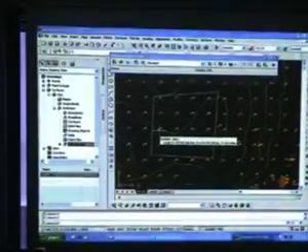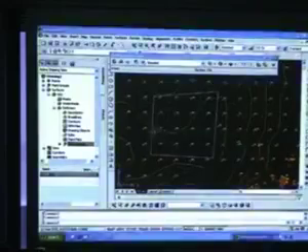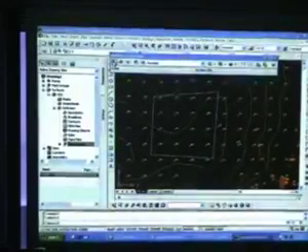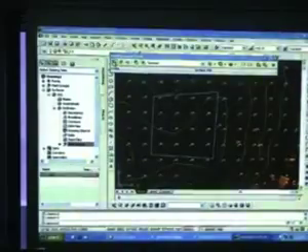What we want to do is grade this platform to the original ground level. First we need to set the grading group, so you select the first icon. By default, it will display the name of the object, in this case a grading group. Next counter means they run a sequential number, in this case grading group 1. The next one will create grading group 2, then 3, and 4. So we'll just leave this as is.